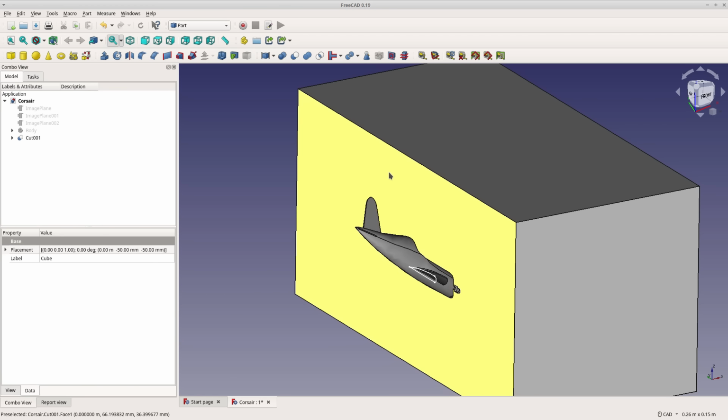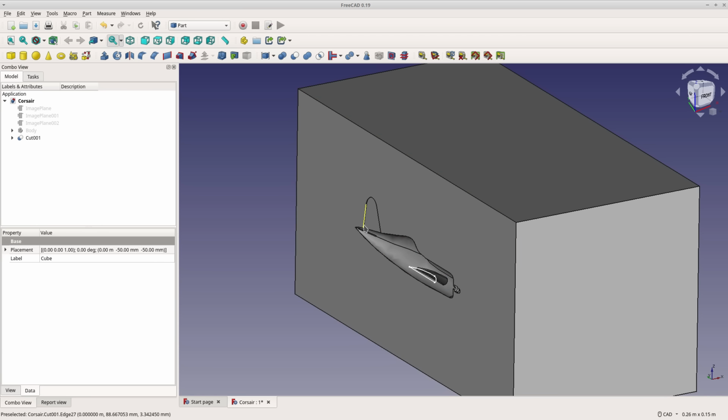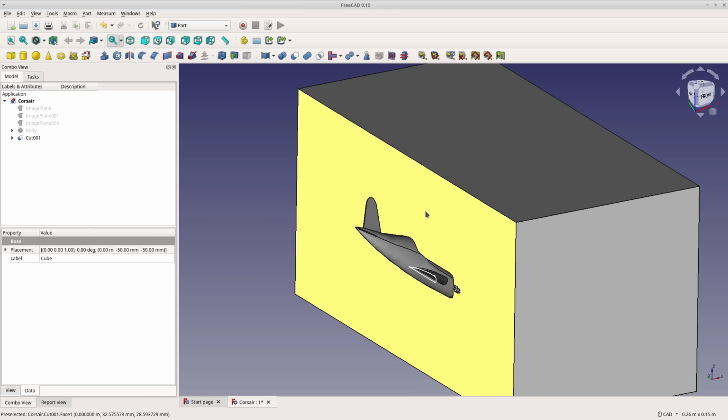Now, you might ask, why not do the whole plane? Well, because the plane is symmetric, we can cut the computation in half by doing half of it. Ideally, you can use a symmetric constraint and have it compute both sides of the flow evenly. I actually haven't gotten that to work, but I know it does work. So when we get there, I'll show you what you can do, even though I haven't actually gotten it to work.